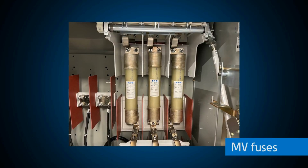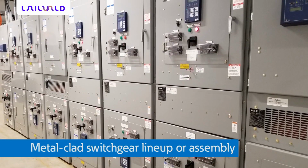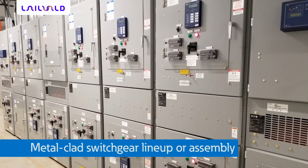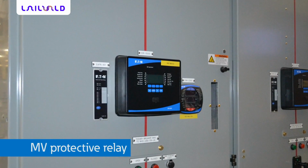Electrical switchgear refers to a centralized collection of circuit breakers, fuses, and switches, circuit protection devices, that function to protect, control, and isolate electrical equipment. The circuit protection devices are mounted in metal structures. A collection of one or more of these structures is called a switchgear lineup or assembly. The circuit protection devices distribute power to various sections of a facility and the electrical loads within those sections. They also provide protection to individuals and equipment throughout the facility by opening at a predetermined overcurrent level, thereby limiting the fault current carried by the system.